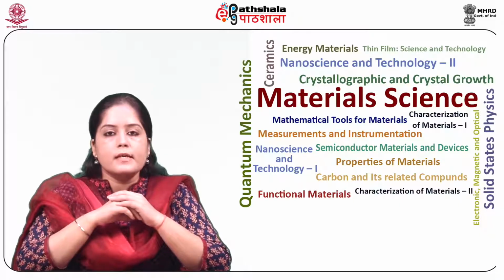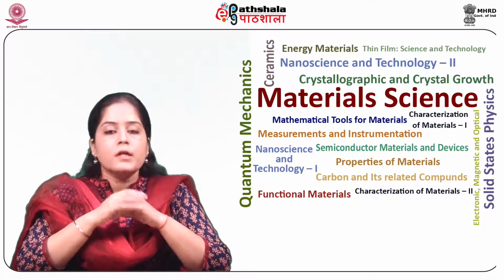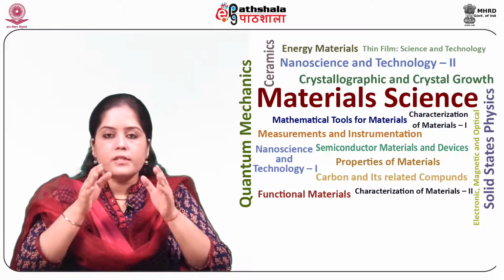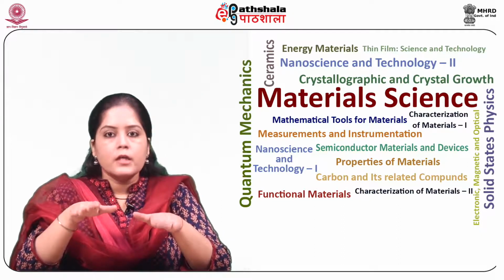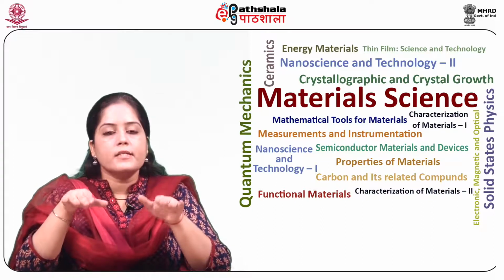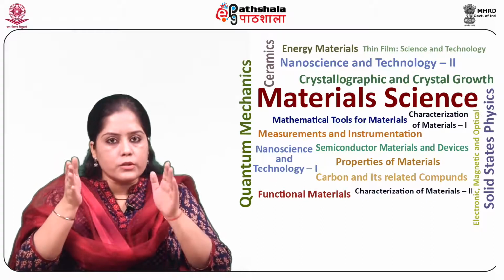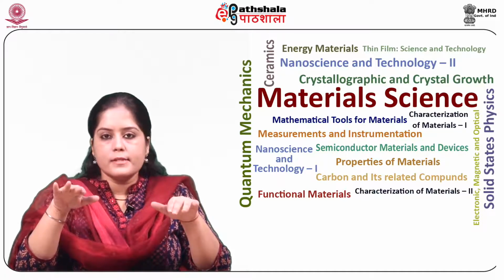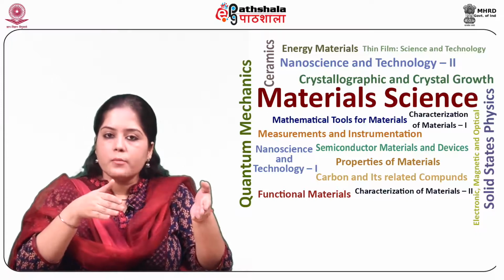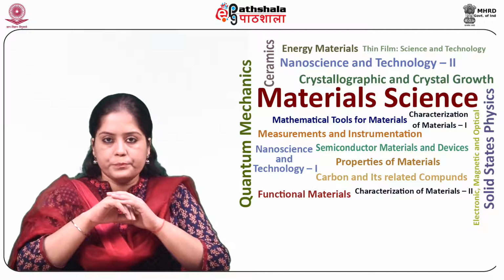So students, let us start with the basic introduction about the module. A transferred electron device is a moderate power device which has low oscillator phase noise, and it is a form of diode used at all microwave frequencies from 300 MHz to 300 GHz.